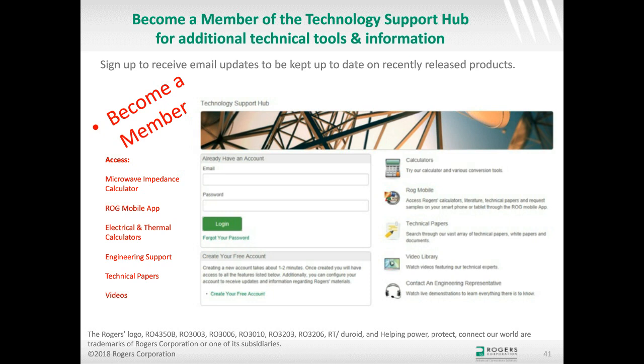The rolled copper is almost always much smoother than ED copper, and there are a lot of different ED coppers out there. There's reverse treat, and there are all kinds of different types of ED copper. In general, for copper surface roughness, rolled copper is the smoothest, reverse treat is a little bit rougher, and then ED is the roughest. There's a pretty wide range of roughness values when you really look at these different coppers too. But generally speaking, rolled copper is the smoothest.